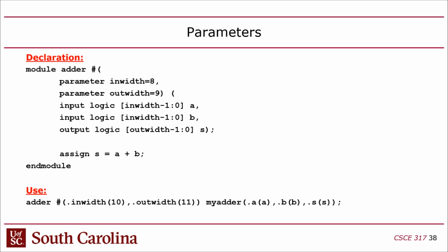But remember, these are just parameters that are basically macros. They're being substituted into the code. These don't represent bits, like signals, right? So that's why they can be integers. Integer is kind of nondescript, right? You guys with me? So I'm not saying how many bits the in width is, because it doesn't matter, because it's really just a macro that's going to be plugged in. Make sense?